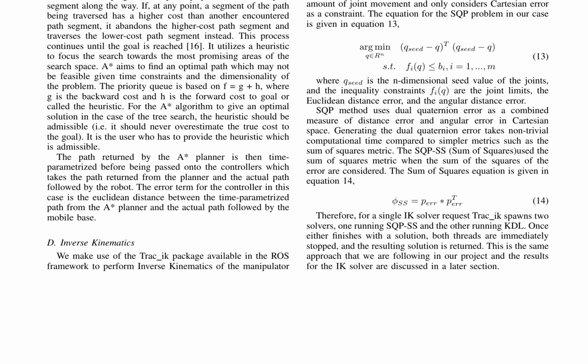This project successfully implemented trajectory control for the Fetch robot, a differential drive mobile manipulator, in a simulated environment. The implementation includes dynamics of the Fetch robot, trajectory planning for the manipulator arm using a quintic spline, and mobile-base trajectory planning with the A* planning algorithm. A state machine for the task of indoor warehouse object manipulation was developed, and the TRAC-IK package was utilized for performing inverse kinematic calculations. The results of the experiments are presented, demonstrating the achievement of the project goals stated in Section I, following the methodology shown in Section 3.